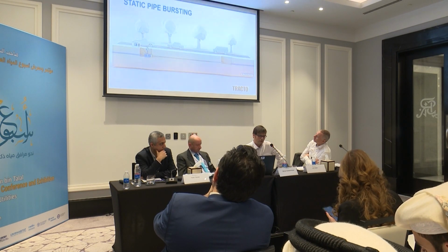Static pipe bursting is actually quite straightforward. You have a pipe bursting rig that goes into the entry pit. It's driven by a hydraulic power pack. With that pipe bursting rig, you push out the rods until you come to the other side. You install an expander to the other side, put your product pipe on the end of the expander, and simply pull the product pipes back. This one is blue, it might as well be yellow, it doesn't matter. We don't mind which utility we're working for.